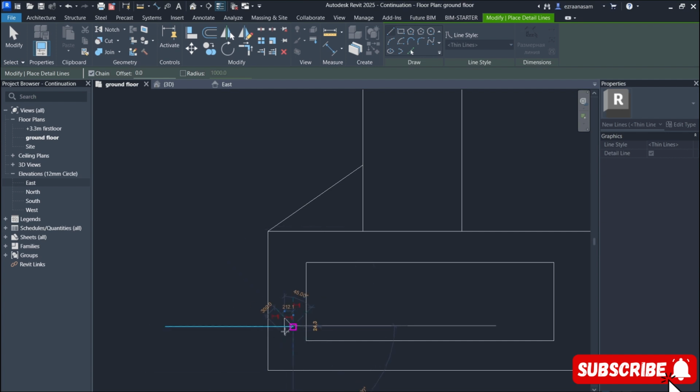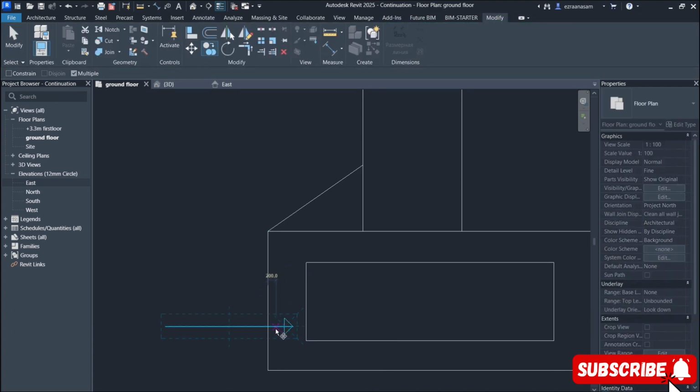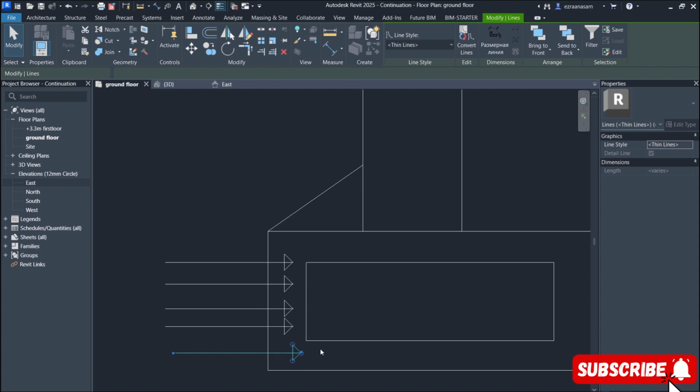There are factors that will be acting on this foundation. And so to avoid these factors affecting our reinforcement, let's say from corrosion or anything, it's always good to extend the cover a bit. When we extend the cover, it still keeps us in line with our structure. It does not change anything.